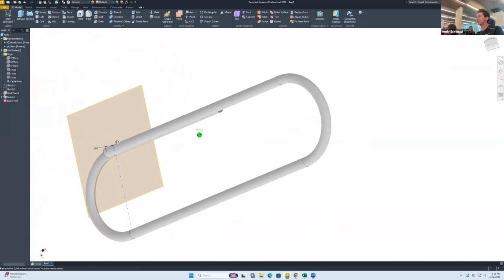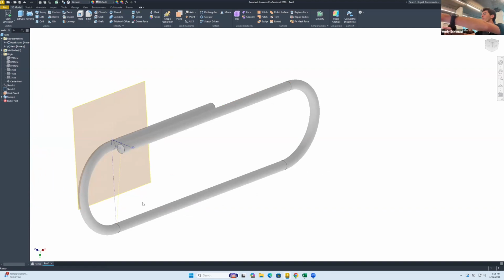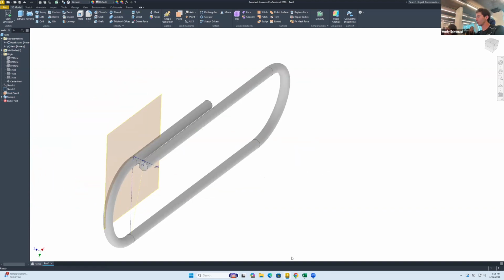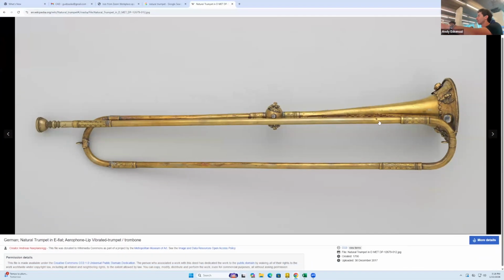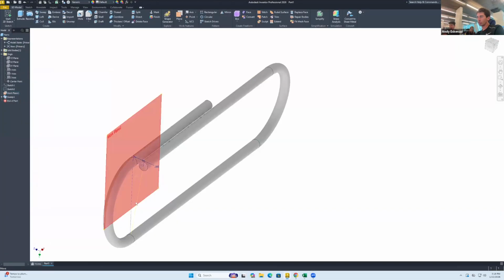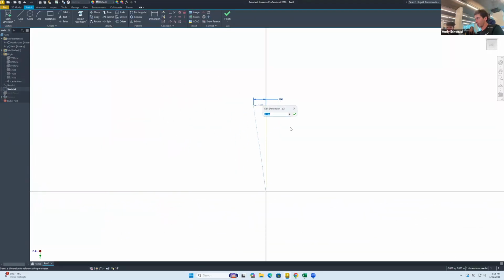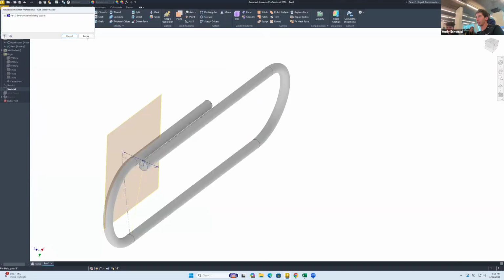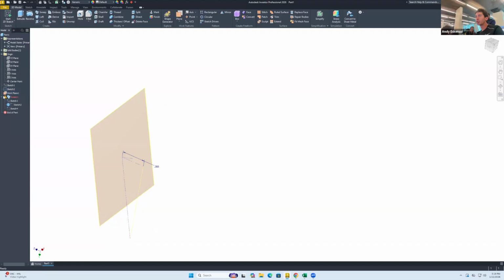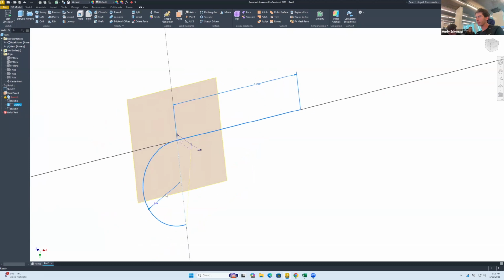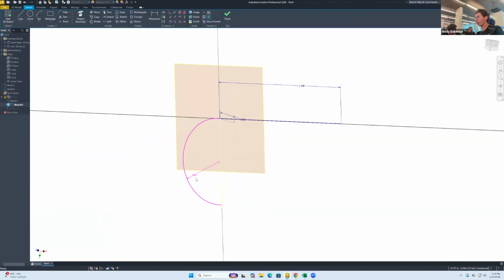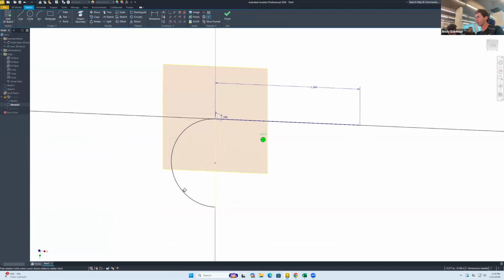Now, what I'm afraid of, and this is something that is super easy to modify, is that we might need to increase that 0.1 to make it a little bit wider. Because when we start working on the bell, we have to avoid any interference. So we can do that by going back to Sketch 2, Edit, and let's make that instead 0.2. Now what's going to happen is that, yes, why is that error? Because we're going to go here to Sketch 3, Edit, and this is wrong, that circle. In fact, let me delete it, there we go. I'm just going to leave it like that.